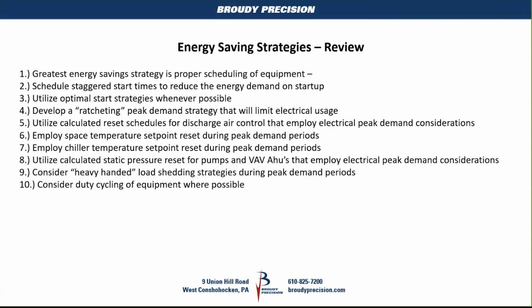The next thing that I talked about is space temperature set point reset during peak demand periods. And this works more so for staged control. That's what I talked about with, instead of maintaining 74 degrees in the space, we get into a high demand situation. We start making, instead of 74, we make 75. On a rise in demand, maybe we bump that up to 75 or 76. But eventually, when we get out of that high demand window, we're going to drop it back down to 74 again.